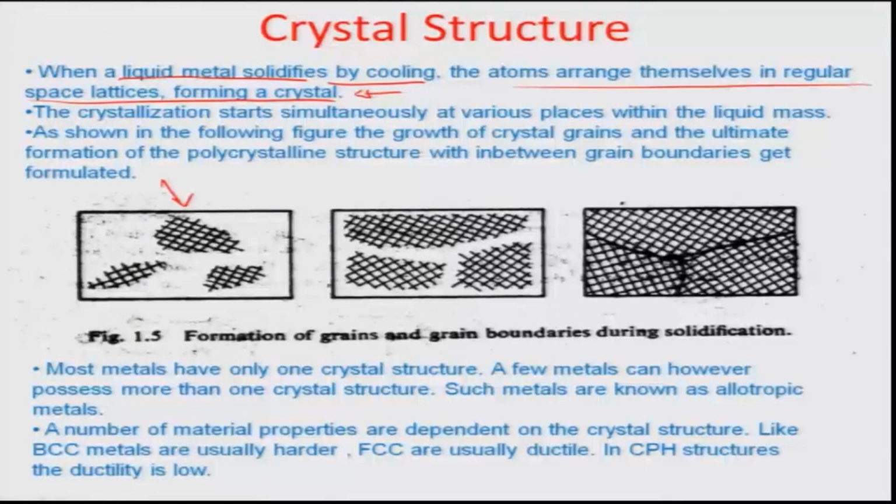As you can see here, the crystals are just about starting to take place. Such centers are known as nucleation centers, where this nucleation center is basically the start of the activity of solidification and regularizing of the unit cells. And these centers are many across the whole liquid stream. Whenever the temperature comes to the solidification point, and that can be anywhere within the liquid matrix, there is development of these small centers of crystal growth.